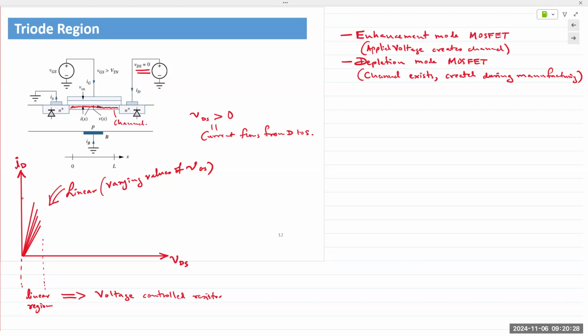Theoretically, it should still work. If the fabrication process is symmetrical, it should still work. Was that the question you had? Theoretically, yes. If it's symmetrical, yes. So the point being made is, if the device is symmetrical, can we simply flip it and call the drain the source and vice versa? And the answer is yes. It will still work.